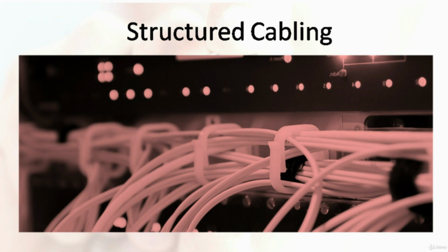If it is buried underground without ducts to protect it, then you will need to specify outdoor cables with armoring, such as external galvanized steel wire and/or corrugated steel tape. The other major component is the connecting hardware, where the most common ones are either 8-pin modular connector plugs and sockets, and the other type is the insulation displacement connectors, also known as the IDCs.